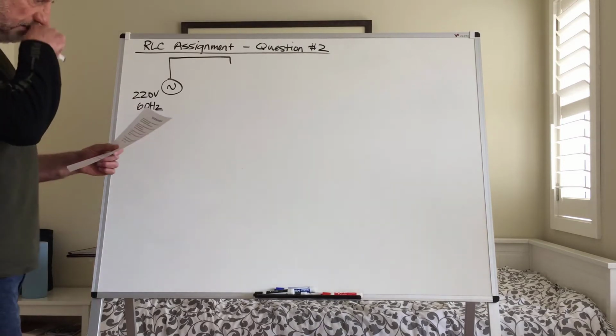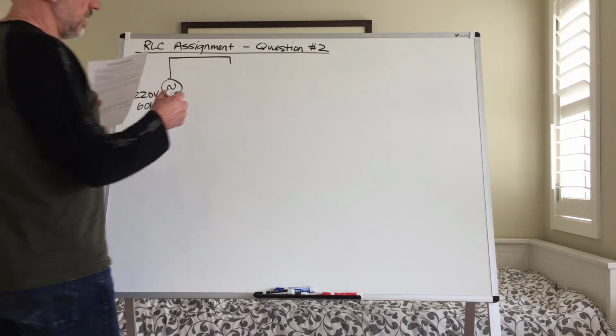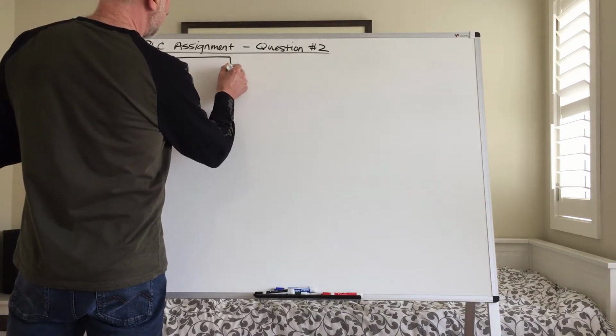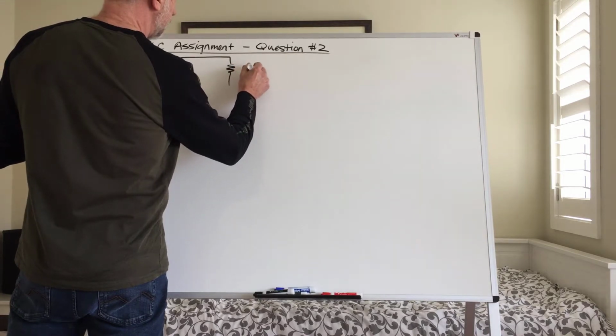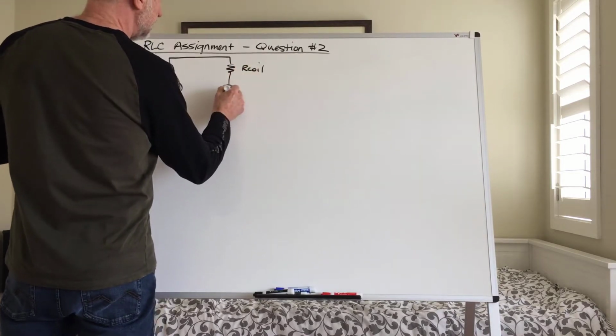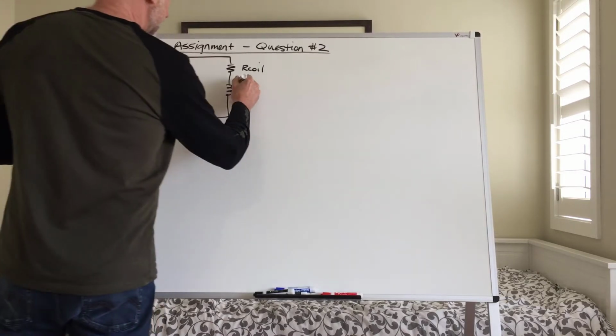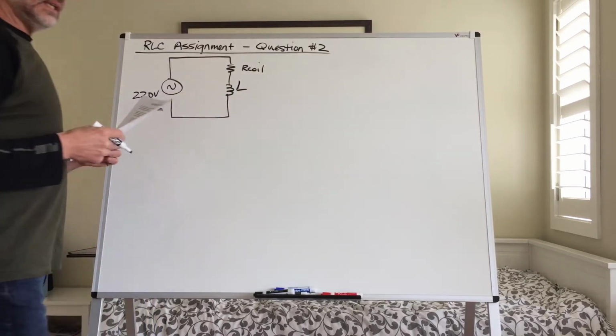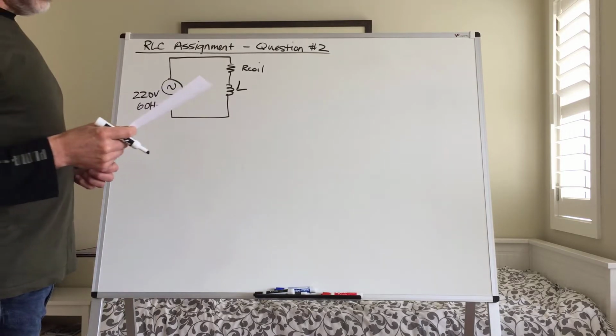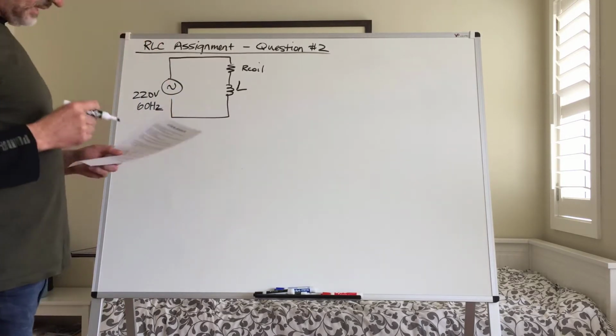And if you remember, when we're talking about a practical coil, the model we use to represent it is an R value of R coil in series with an L value for an inductor. So here's our L value. When we're modeling that, we show a series connection.